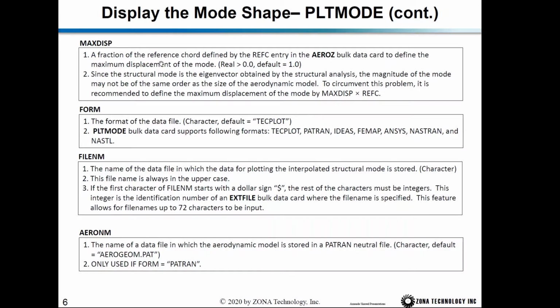So you use this fraction, which will be multiplied by the REFC entry in the AEROZ card to define a factor, and this factor will be used to multiply all the mode shapes. Because the mode shape may be very small or very large, since it's an eigenvector, you use this entry to control the maximum displacement of the spline mode on the aerodynamic model.